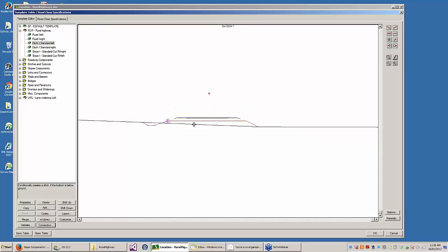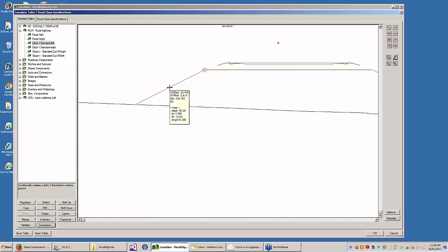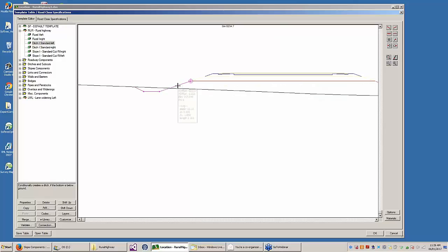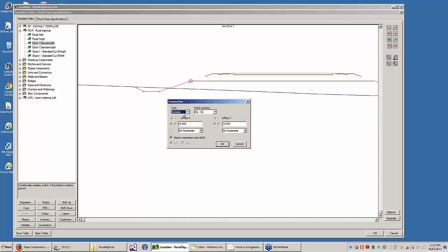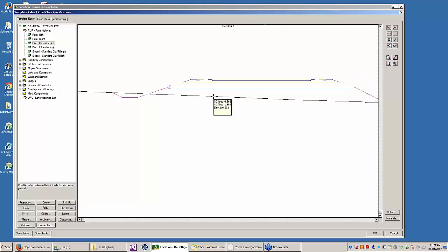One of the things, though, I wanted to say was that you can't always attach something to a point code. If we go back up here, this slope line is attached. It looks like that slope line could just be attached to this point code, right? It says REL. However, if I come down here and the ditch component kicks in, attaching the slope to REL would not give me the result I wanted, because I'd have a slope coming from REL and heading off and covering the ditch. So it's generally useful to connect things on the outside of the template, and that's why this outside is there. You just have to be a little careful creating templates and making sure that instead of explicitly attaching them to point codes, you attach them to the outside.